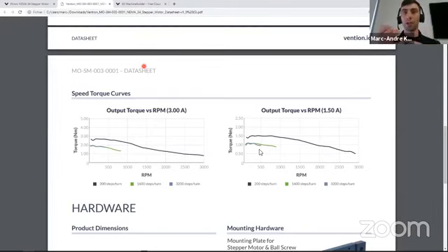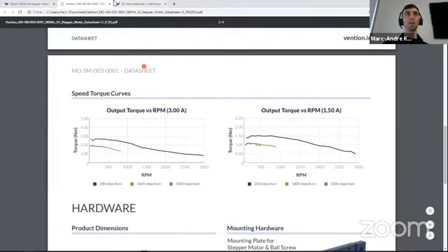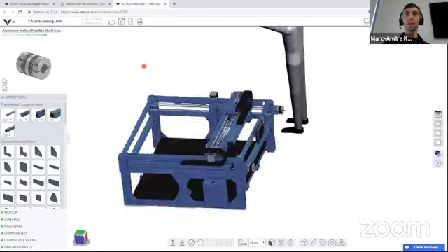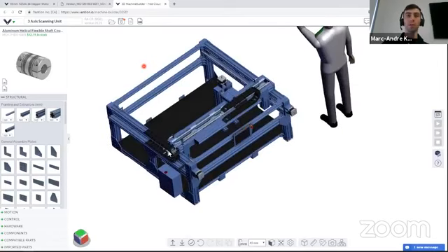So you have option A to microstep, and you have another option that would be to use our 5-to-1 gearbox. It's going to reduce the speed and increase the torque. So those would be different options that you have. Now that you have found that the small stepper motor is going to be sufficient for both of those x-axis, you can repeat the process again for the y-axis and the z-axis.